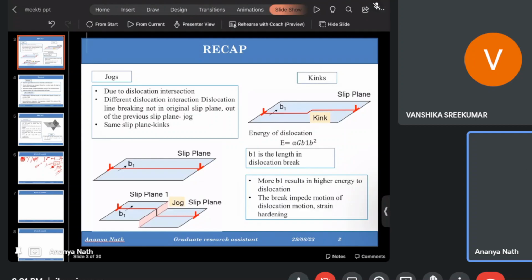And ma'am, can we have a good bonding between the same heat treatable alloys, like the second series or... Yeah, people are working with the 6000 and 7000 series. Obviously the things are not very easy because the alloying elements are different in both cases. So they are trying different processes to get an optimum bonding between them. I have seen some research works going on where they are trying to join 7000 series with 6000 filler rod, but it's a good scope of research.